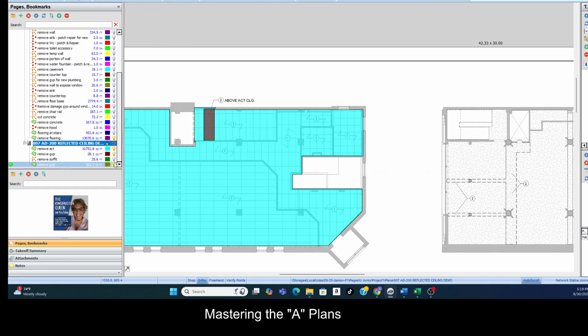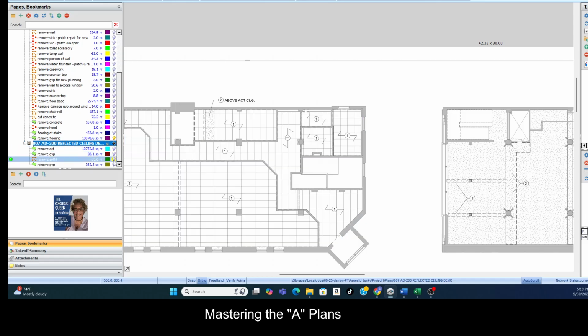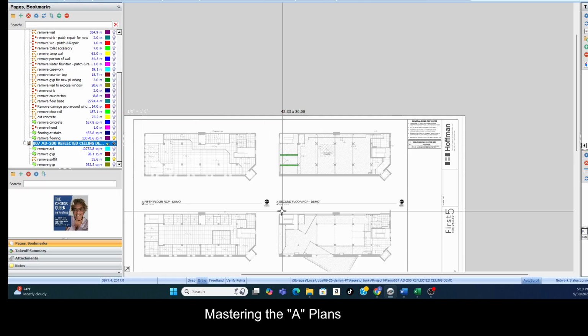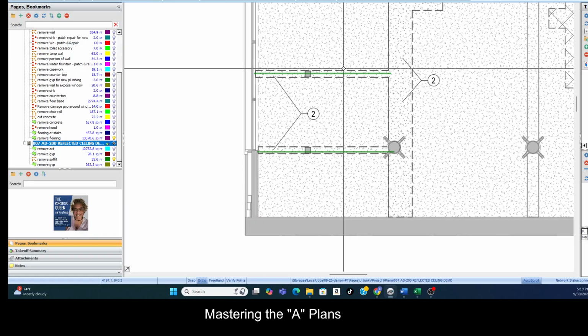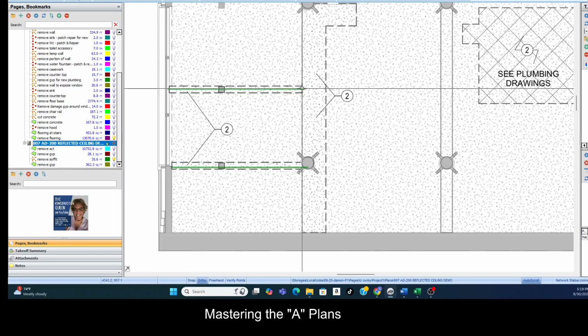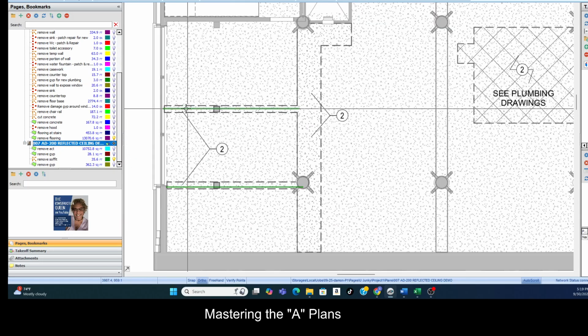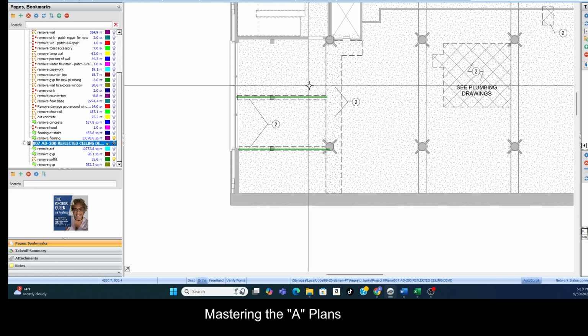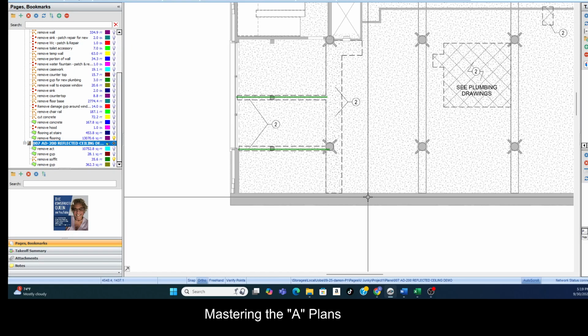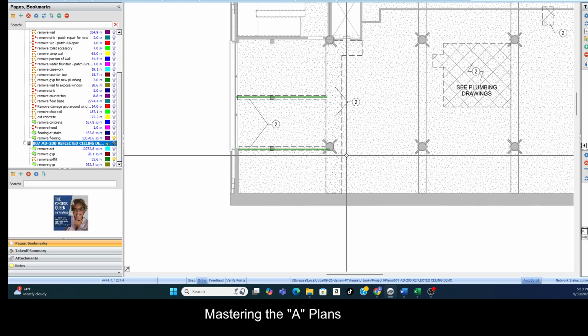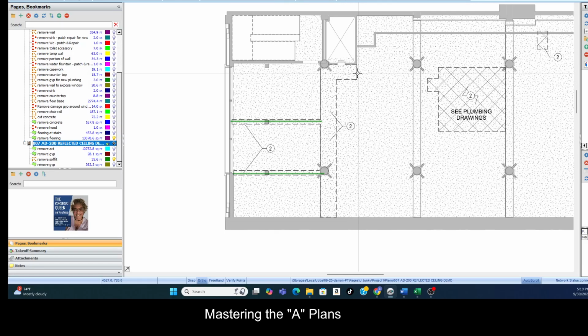And the soffits, let me take that off. So a soffit is right where they have a portion of the drywall that's going vertically down. In a good set of plans, we'd have a section view so we could really determine how far down that's going, so we can determine a square foot amount. I doubt that this is just drywall, flat. It usually indicates it's a soffit of some kind. And this one too, it comes down 3 feet.